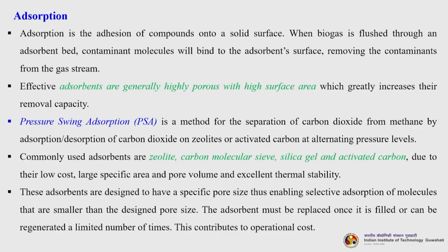Commonly used adsorbents are zeolite, carbon molecular sieve, silica gel and activated carbon due to their low cost, large specific area and pore volume and excellent thermal stability. These adsorbents are designed to have a specific pore size, thus enabling selective adsorption of molecules that are smaller than the designed pore size. The adsorbent must be replaced once it is filled or can be regenerated a limited number of times. This however contributes to extra operational cost.